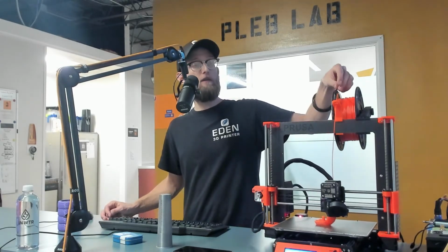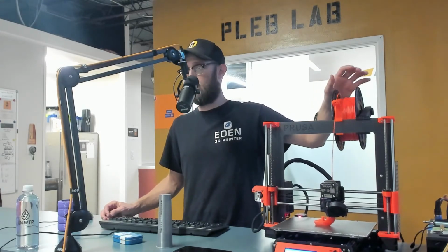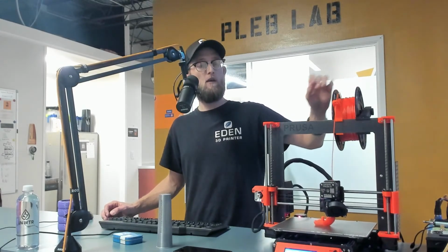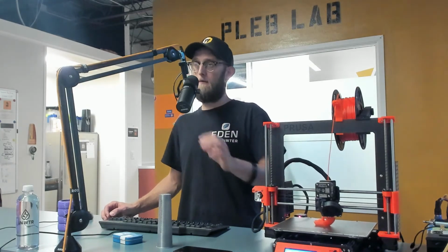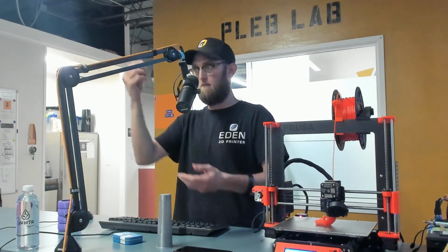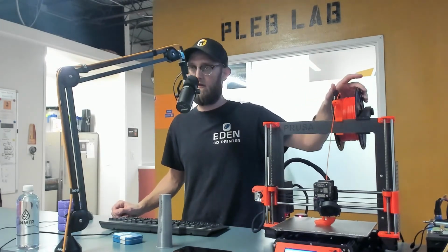You will actually get, nylon is atrocious with this, higher temperature nylon. And I actually noticed it here with some of my other filament that I had left out. Sometimes there will be so much water in there, I'm being a little exaggerative, but you'll actually see a puff of vapor come off the top, and that's just water hitting a 400 plus degree hot end. So it's very helpful to keep your material dry. And if it's not dry, be careful.